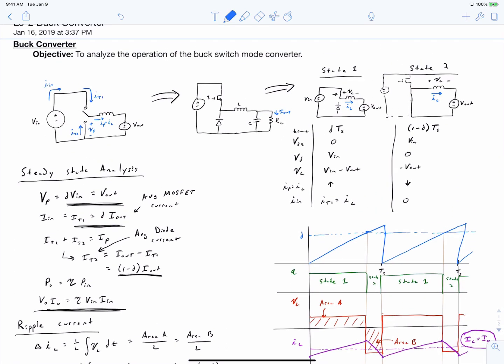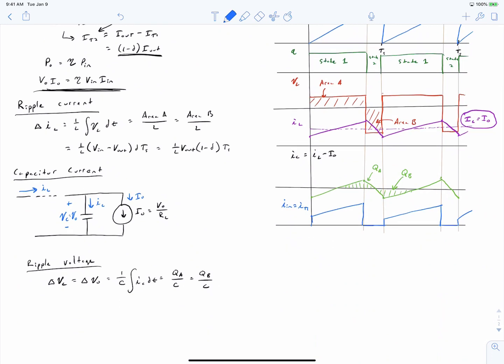So in the diagram above, we've shown just a voltage source, but if we need to filter it, we might have a circuit that looks like this. So here's our source. We might place an LC filter connected on the input, which is composed of an inductor as well as our input capacitance. So you can see that while this current right here, if we call this IN, can fluctuate according to the blue waveform, the source current, IS, can be designed to be very stiff. It can be a DC value.